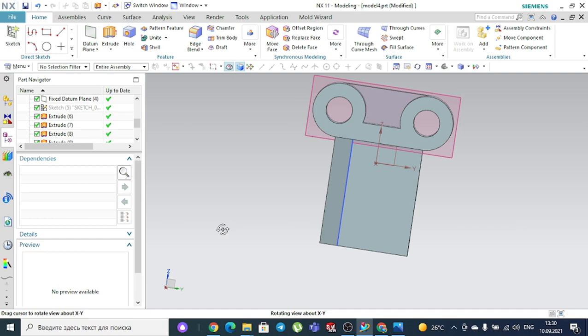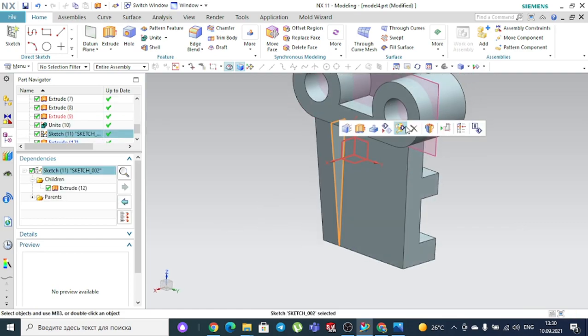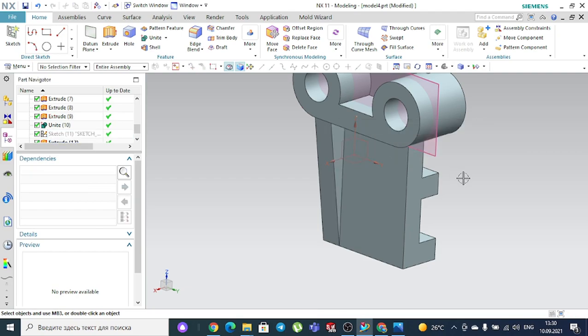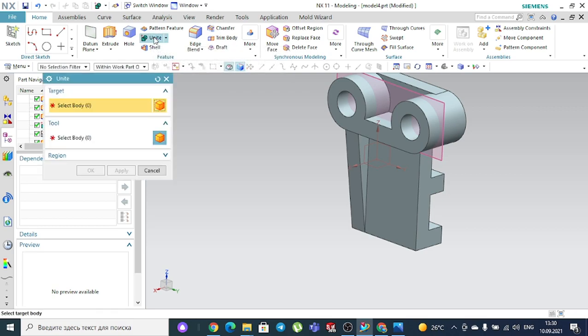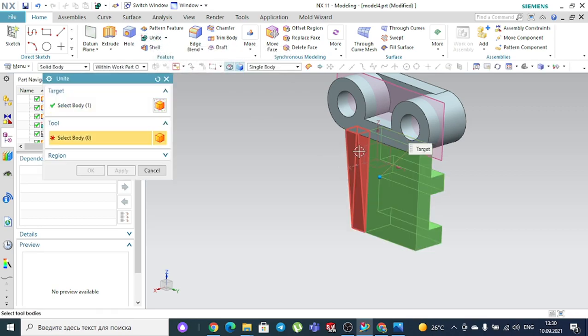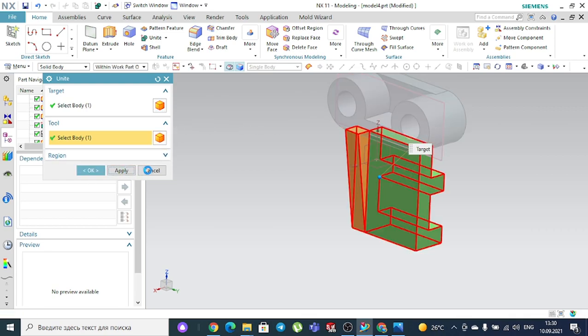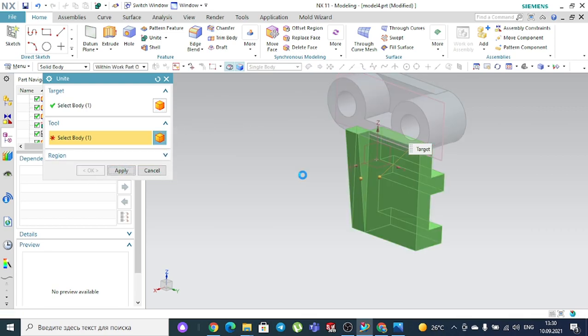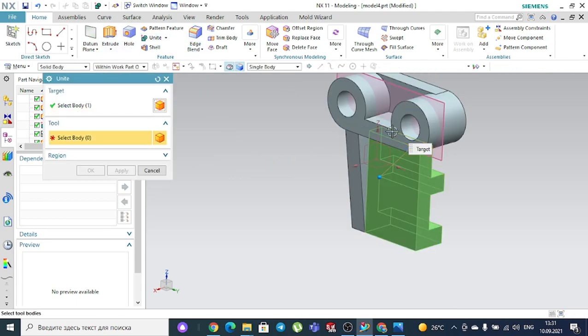Now it's okay. Then since we can hide this one, this system and this systems all is not united, we can use here the unite function. Also you can unite this one, and just a moment, you can unite this one with this one, apply.